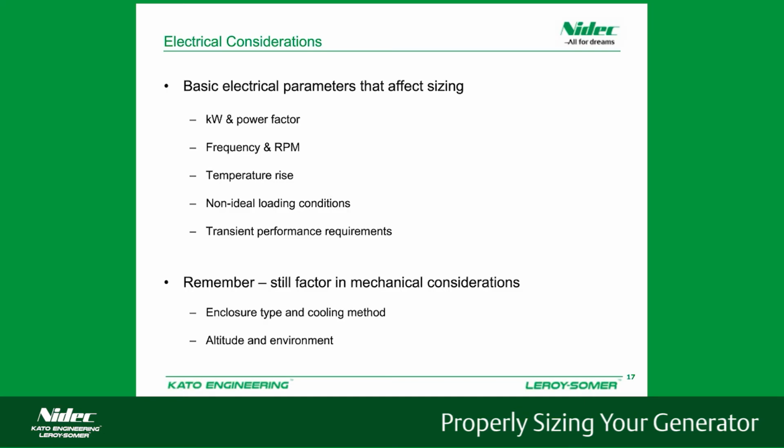So our basic electrical parameters for affecting size are going to be our kW or kVA and power factor, our frequency and RPM, our temperature rise, any non-ideal loading conditions, and any transient performance requirements. So still remember to keep the mechanical considerations in mind.